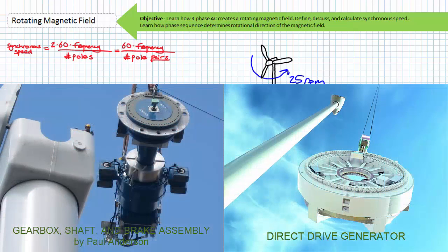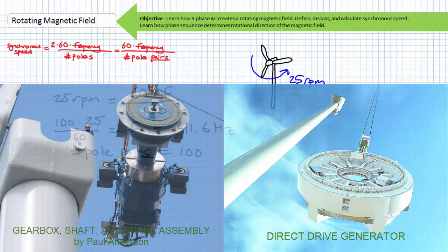There are advantages and disadvantages to both approaches. Gearboxes might be costly to maintain in remote offshore environments. However, direct drive generators, because of the sheer number of poles that must be incorporated, have very large diameters and are exceedingly massive and costly. All these costs and benefits need to be considered as technology advances.